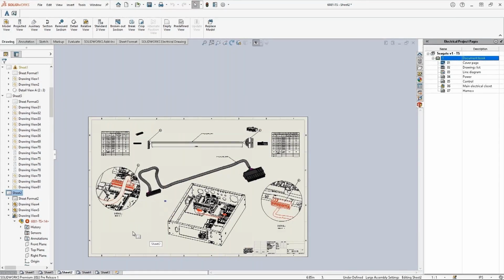The same holds true for this drawing. Every callout is automated by the system. You might notice how in the detail views you're seeing some red. I was able to play with SOLIDWORKS layers within each one of these views, so I could highlight this particular harness or cable assembly, whatever it may be, in this particular red color.